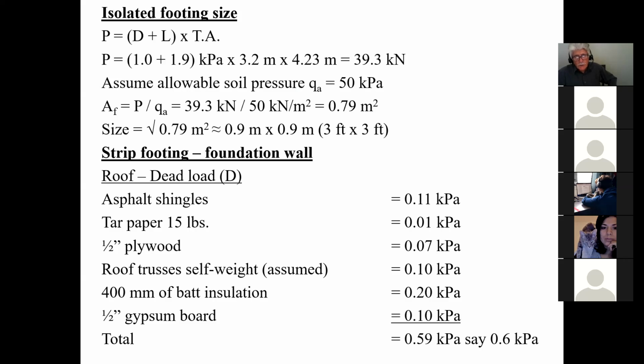Easy enough? So just for general information, when you were talking about the asphalt shingles and how they come in like 235, 24, where's that specified? Is that specified when you buy? They used to specify it right on the package. Exactly. In other words, if they say it's a 15-year shingle, most likely it's a 210. They say it's a 25-year shingle, most likely it's a 225. They say it's a 35-year shingle, it could be a 235. You understand? So that can be right on the package.